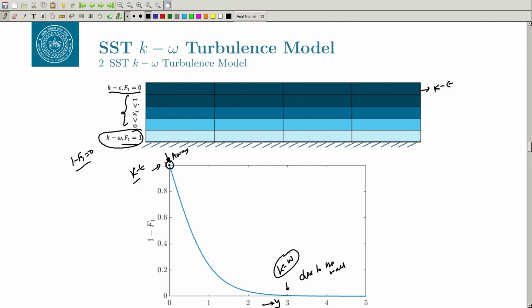to 0. It is not like at one grid point you have k omega and at another point k epsilon, right. So, this is k omega and this is k epsilon. It will be a problem, because you are making a drastic change, and a drastic change is not good in any CFD simulation, whether it is a drastic change in the grid or in the flow parameters. The solver always has difficulty if you have a very drastic change.